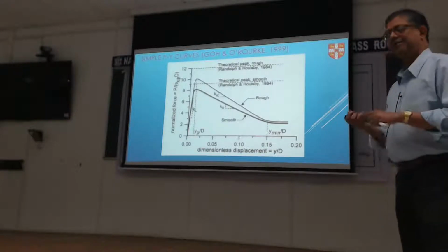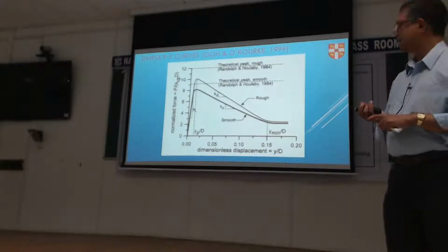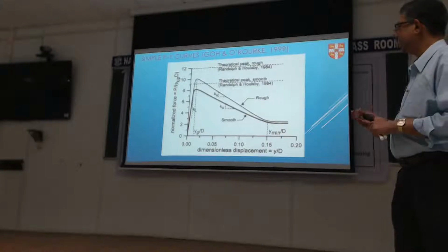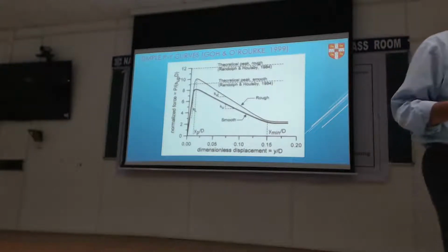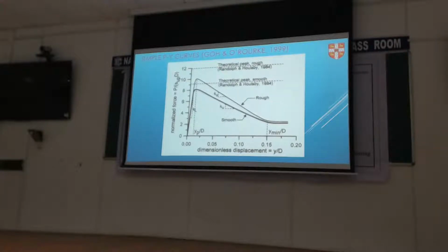So they first separated out the smooth and rough piles. And now that is important because our steel piles, you normally consider them to be quite smooth. Concrete piles, probably on the rough side. You sometimes put coatings on piles to make them rough and to protect them in other ways. So you want to know that's a parameter. So they considered those two to be separate.